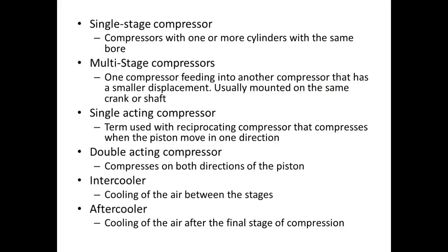We have a single stage compressor. This is when we have 1 or more cylinders with the same bore. We have multi-stage compressors, where we have at least 2 cylinders or multiple stages. And we take the compressed air out of 1 stage and feed it into another stage. Everybody okay? And the more stages you have, the higher the pressure. We'll look at a single acting compressor. This is what most of your compressors are. Double acting compressors actually compress on both sides of the piston.